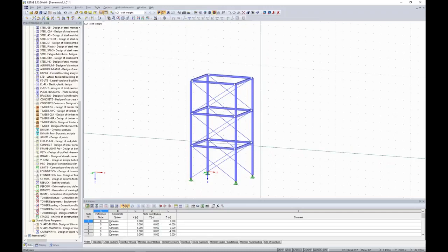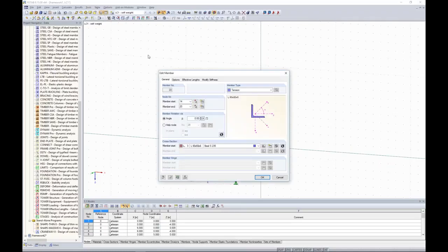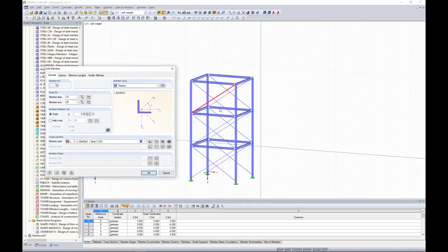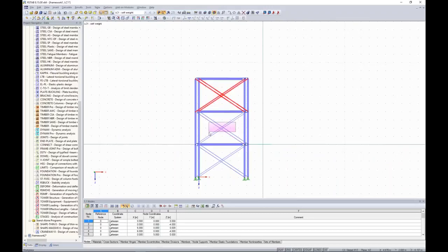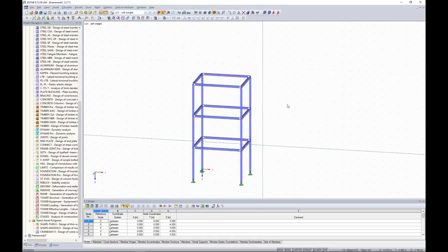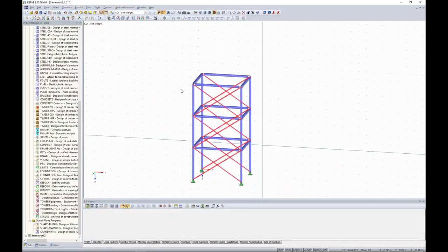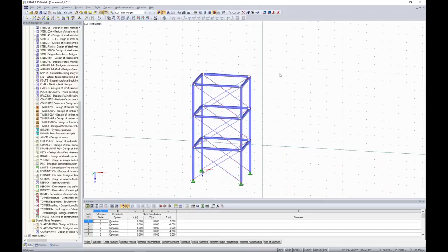So this is a very common case of tension members. And you can imagine if you have self-weight load case and you calculate the first iteration, probably all the tension members have compression. And in the calculation, they will be removed in the very first iteration at the very same time. And if you imagine this exact structure with all of the tension members, let me just remove them, it's going to fall aside, and that's the instability. How can you fix it?